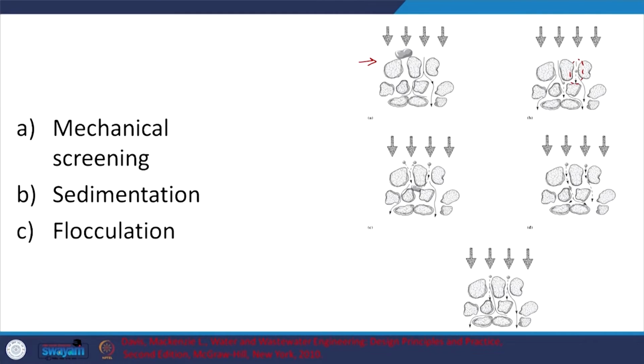And flocculation. Again, if the particles have been destabilized by coagulation earlier, flocculation can take place even within the media. It is pretty representative here, but it is not the only way that flocculation can occur. Particles can flock together or aggregate because of differential velocities due to either the fluid or the settling velocities, and you can end up having flocculation here. And interception.